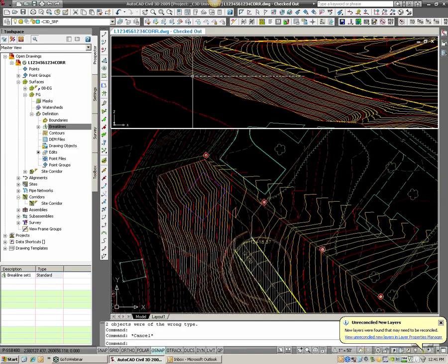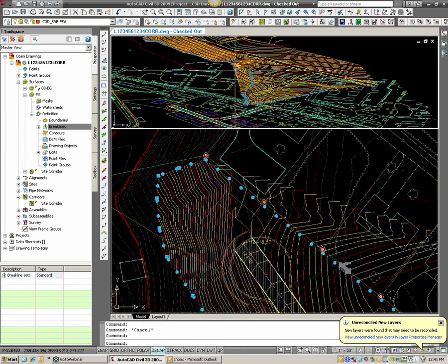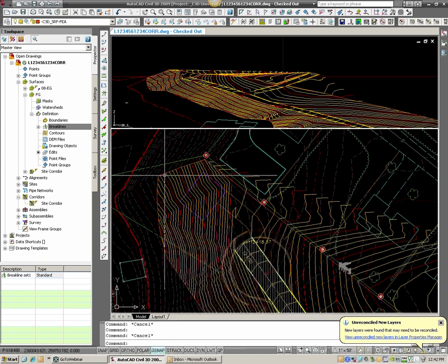It's a 3D feature line. You can see it selected, and it was already draped onto the surface. I already did these steps to speed things along. I just want to offset this out and down. So if I use my normal AutoCAD offset command, it will just offset the feature line out, and it won't change any of the elevations, which I need it to.